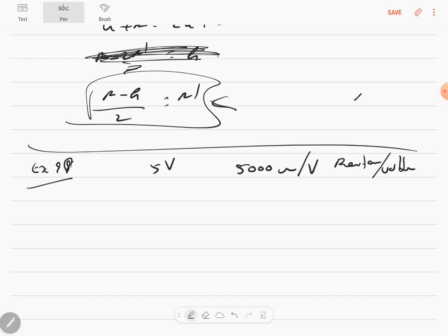The voltmeter reads 5 volts full scale deflection. Actually, this question is about a galvanometer getting converted into voltmeter. So when we read, we should only think of a galvanometer which is converting itself into voltmeter. Voltmeter now reads 5 volts, which means the maximum voltage is 5, or there's 20 volts here. So the maximum voltage is 20. So let's see the question. The voltmeter reads 5 volts and shows a full scale deflection and is graded according to the resistance per volt for a full scale deflection. It's got 5000 ohm per volt to be the resistance.